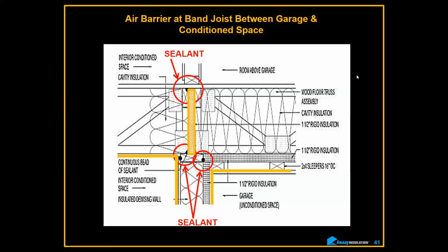It's very important. And the problem with it is a lot of times when they're using a truss or a TJI, then you've got to cut around everything. There are so many ways to do it without having to mess it up, and it's quick and easy. You could hang the joists even though they're sitting on something. Put a full rim board across there and forget about it. You're completely done. So, easy ways to do stuff. Cost you a couple of extra bucks. If you're doing advanced framing, no big deal. You just save 10% of your lumber right out of the gate. Not only that, it's probably faster and quicker in labor than it is to start cutting around every cavity.